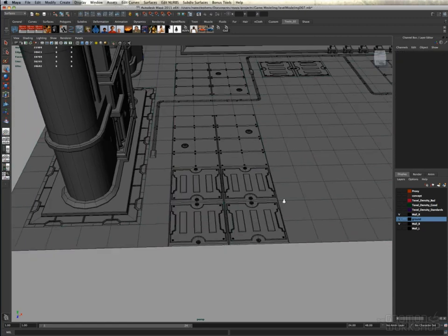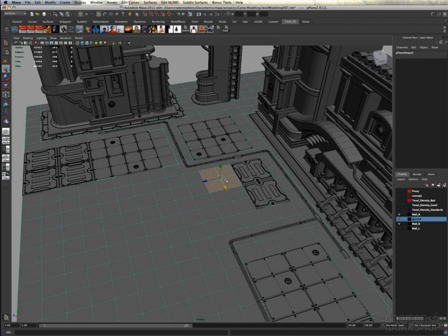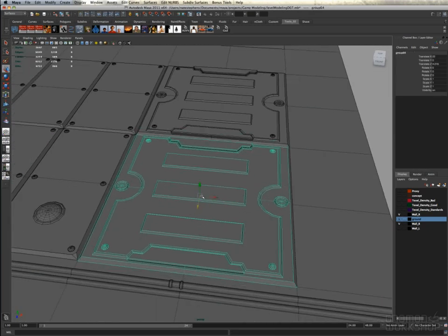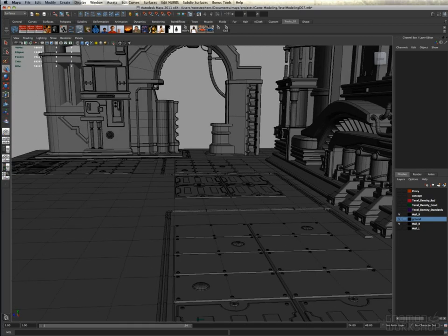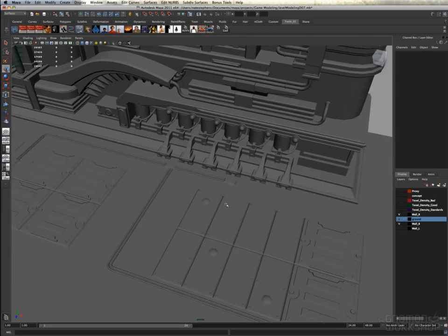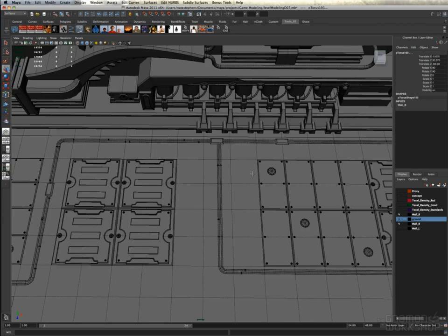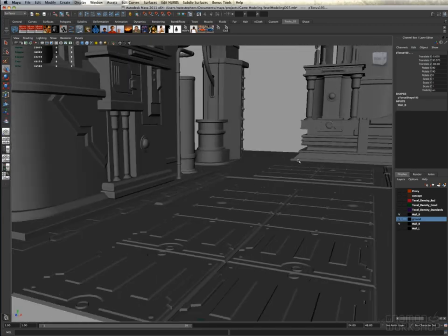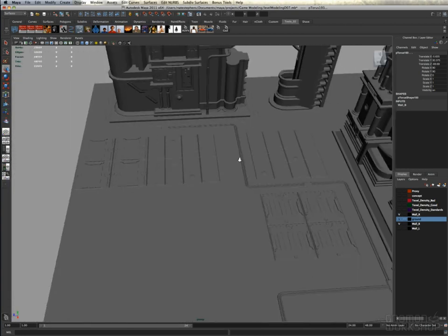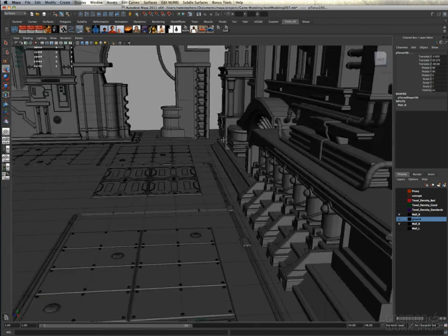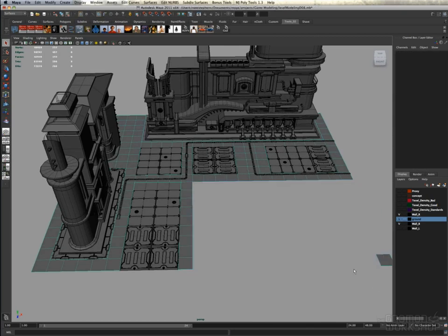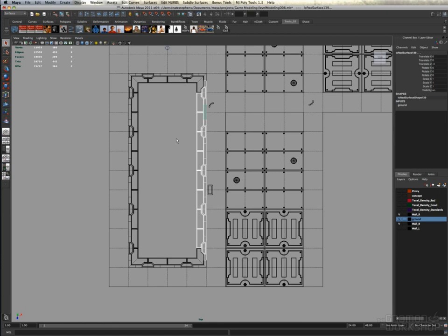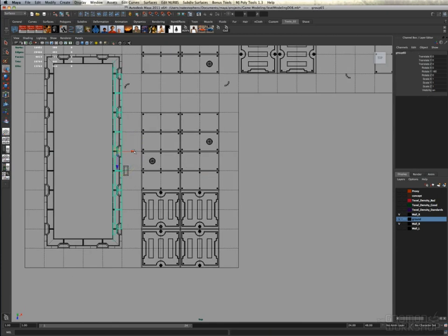There we go. Go ahead and duplicate those over there again. And these, we have two groups of 4 of these guys. Again, check that glancing angle. Do that with wireframe off, just so I can see how everything's lighting up. You'll see at this stage I'm doing that quite a bit. And we'll just go ahead and clip out a big section of the floor right now. We'll pretend that that's an area the player is not going to go.